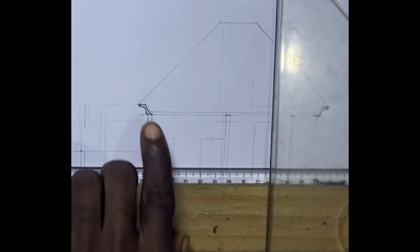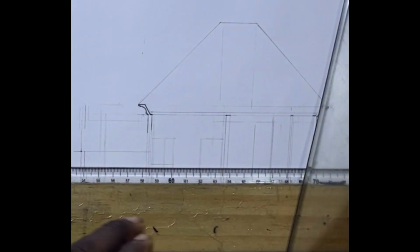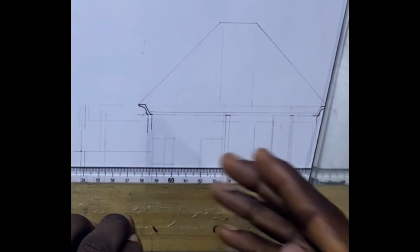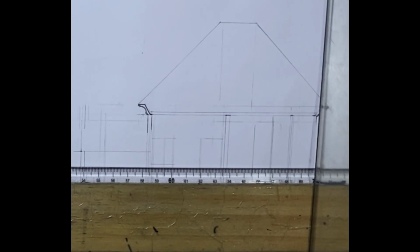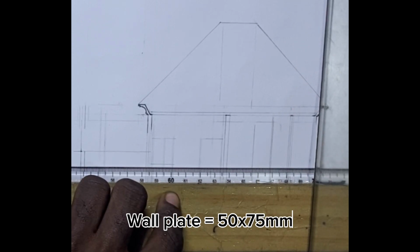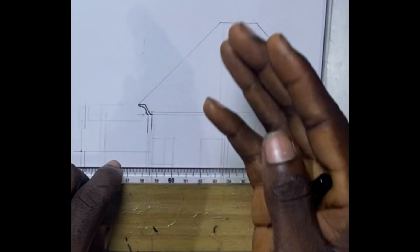Alright, so after taking our concrete fascia board, what next is to have our wall plate just on our wall, and we all know that wall plate is at times in the dimension 50 by 75. The 50 represents its thickness while 75 is its height.